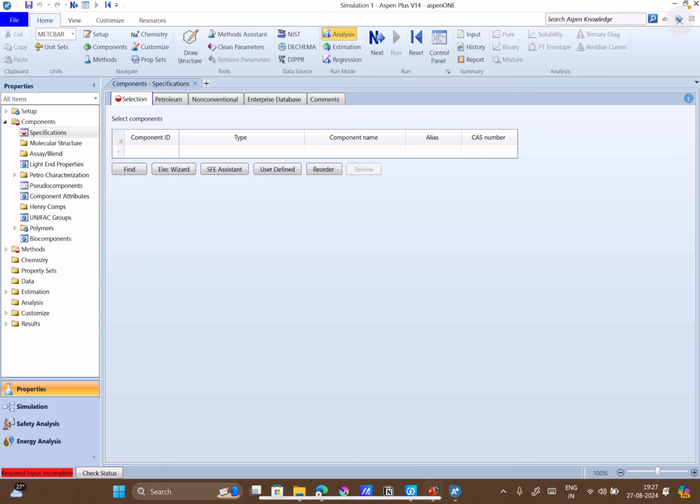Now here you can see the envelope within the tie lines, within the phase boundary. That will show the liquid-liquid equilibrium, where if we are in between any point, if you recall the mass transfer phenomena, two phases will be separated out. Okay, one will be extract and one will be raffinate. Outside this phase envelope, we will have only a single phase, the mixture of our three components. Okay, and if you want to do liquid extraction, we should be within the phase envelope, right?